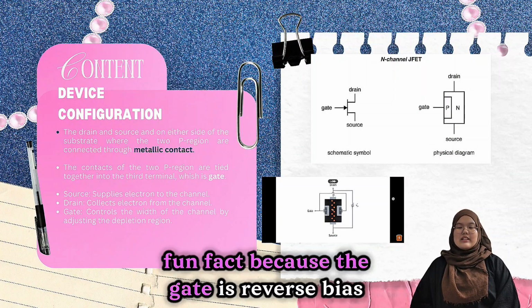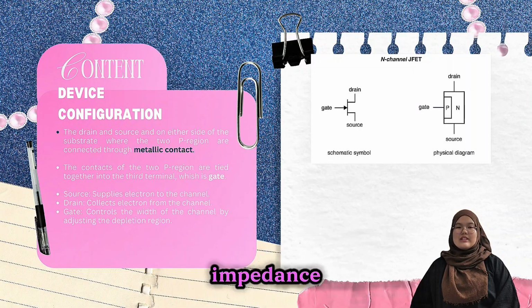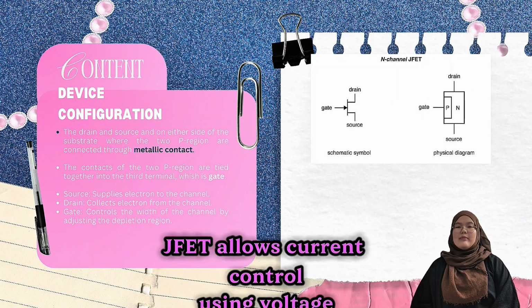Fun fact, because the gate is reverse biased, the gate current in a JFET is almost zero. That's why JFETs have a very high input impedance, making them excellent for amplifier applications. So in summary, the device configuration of an N-channel JFET allows current control using voltage, making it a key component in analog electronics.